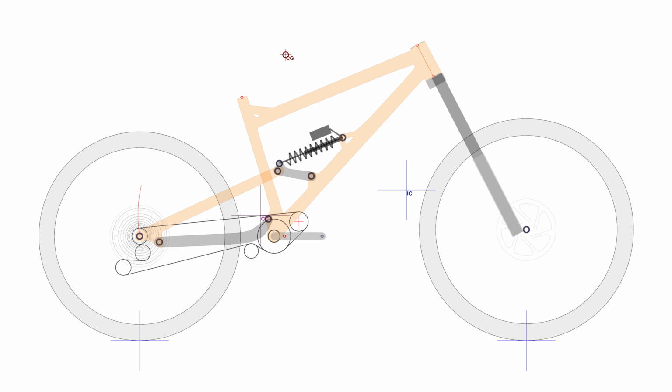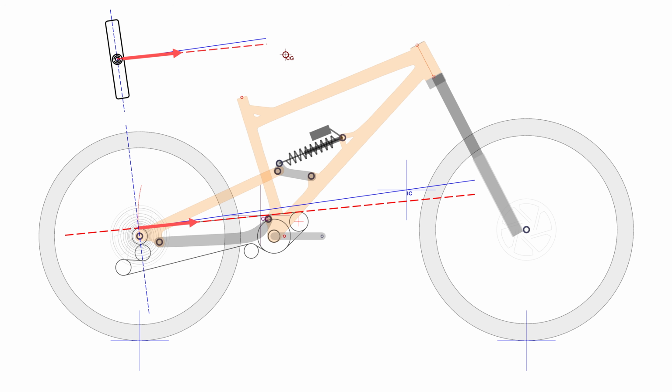However, instead of just motors, most of us use a chain drive, and the chain introduces its own additional effects. When a force is applied at the pedals, it will tension the upper part of the chain. This active segment is what's responsible for the driving force at the wheel. The line along the force vector where the chain meets the cassette is called the line of action. In the model shown here, the line of action is running at a downward angle when compared to the IC perpendicular. Thinking back to our slot analogy shows that in this case, the pulling force from the chain will try to pull the suspension down. In terms of rotation, we could say that the chain line passing above the IC is inducing an extending motion, so the chain contributes to the anti-squat moment.